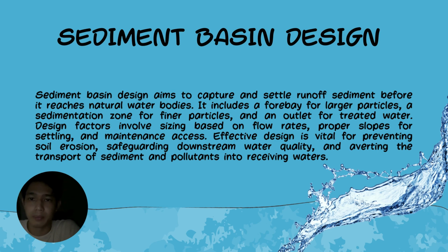about sediment basin design. Sediment basin design aims to capture and settle runoff sediment before it reaches natural water bodies. It includes a forebay for larger particles, a sedimentation zone for finer particles, and an outlet for treated water. Design factors involve sizing based on flow rates, proper slope for settling, and maintenance access.